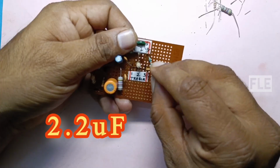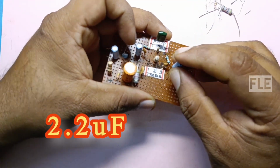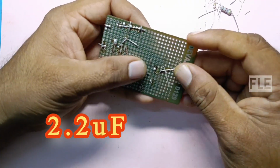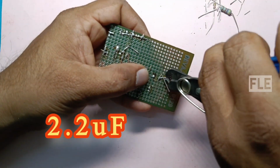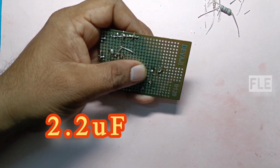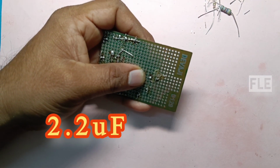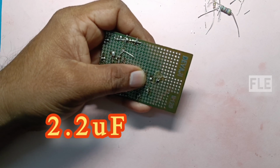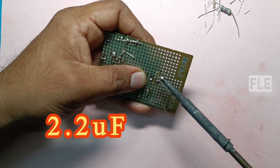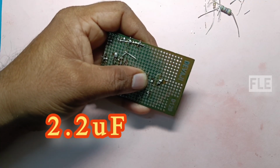One 2.2 microfarad is connected to the common terminals of 332 pF and the 10K resistor, and another 2.2 microfarad is connected between the 5.6K and 6.8K resistors. Always refer to the circuit diagram while inserting components on the PCB.